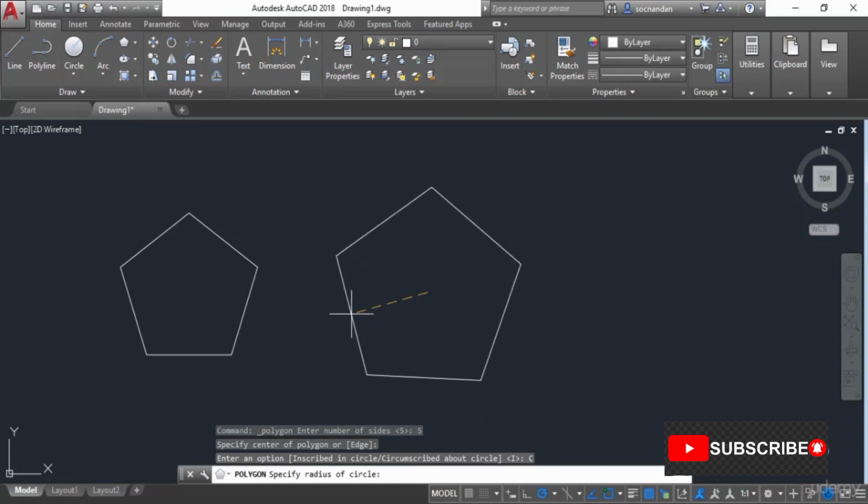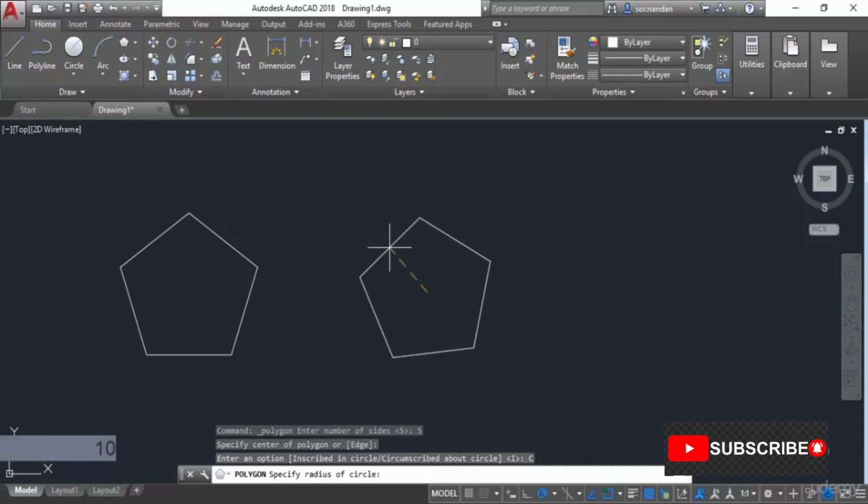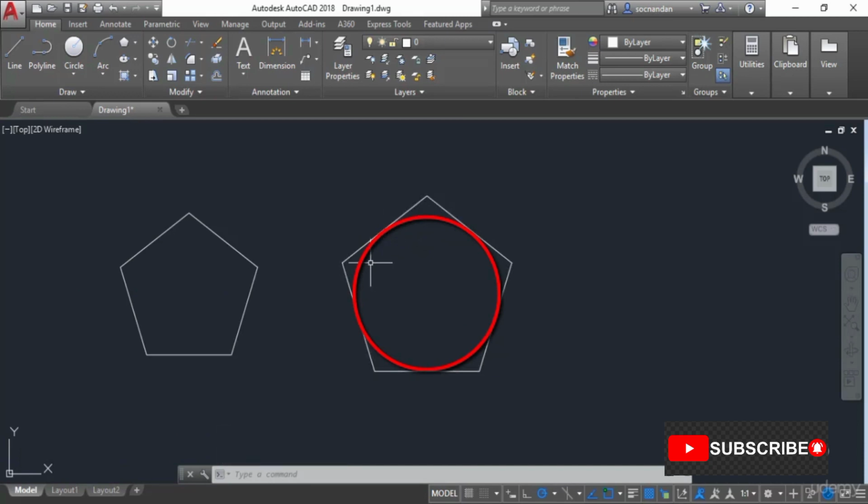So now you need to click anywhere to specify the size of this polygon, or you can also enter the radius. So in this case also, let's enter 10 as the radius, and now we are entering the radius of this circle which is inside the polygon, and the midpoints of the sides are touching the circle. So here we have the same polygon which is inscribed in a circle of radius 10, and here we have the polygon which is circumscribed about a circle of radius 10 units.